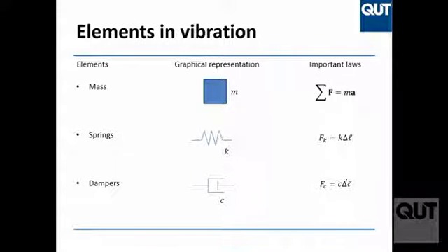Good, so we want to study vibration to see how much our system, our particle, vibrates given a certain situation. And today we look at free vibration. There are two main distinctions of vibration, free and forced. Forced means there is an actual external force which keeps the body vibrating. For instance, take this beam. If I continuously hit it, my hand continuously applies a force to this beam, and it continuously vibrates. Makes sense, right?